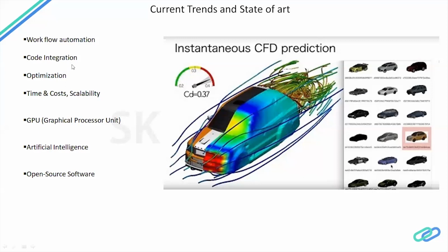And sometimes we need to deal with fluid behavior with respect to the structure. Let's assume whenever the fluid hits a structural body at higher velocities, the structural body may deform or fail. For that type of scenario, we need to do CFD with integration with some other structural solvers. So we need to develop the integration between CFD and structural in FSI problems.